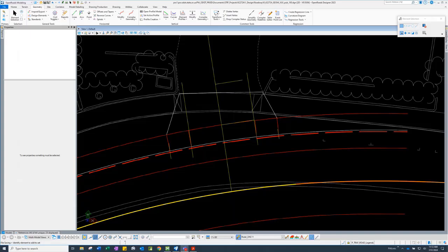Until people put things in the chat, I would like you to move your mouse over the match feature definition button. You wanted to highlight that you're using the match. It's just to the right of the down arrow in the feature definition toggle bar. And it's a one-shot deal, right? So you can select any, and it changes. And actually, it's not a one-shot, it stays in it. You can continue to change it. You can say, oh, that wasn't the one I wanted. You can just select until you have the correct one reading in the window. And then escape gets you out of that command.